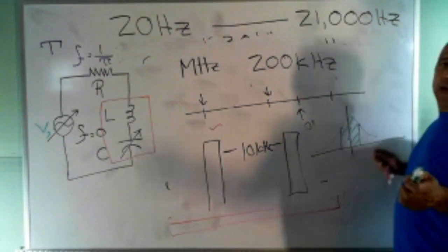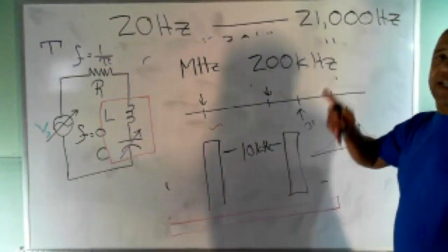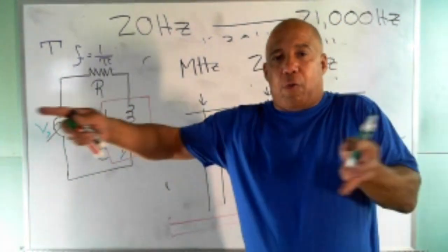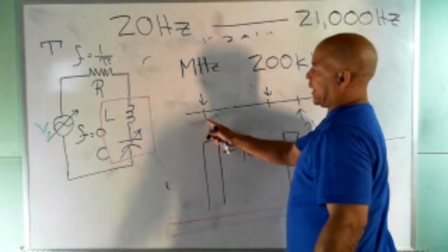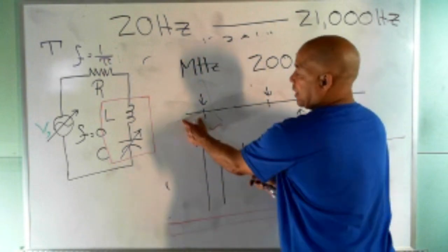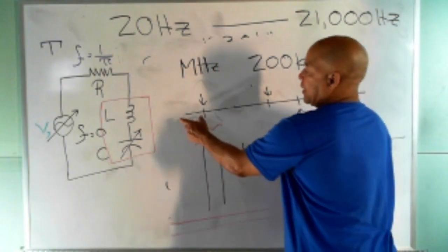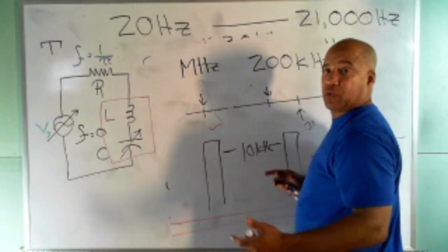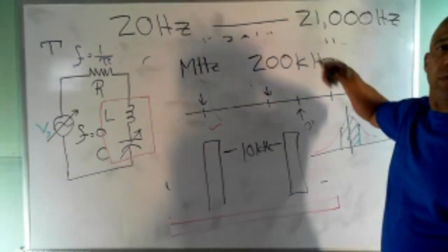When you tune the radio, when you go from one station to another, what you're doing is you're changing the resonant frequency. By changing the capacitance, you're moving that whole band up and down. You can move it up. If this is your resonant frequency, you pick it up. That center frequency F sub R, and then 5 kilohertz this way, 5 kilohertz that way if it's AM. If it's FM, it's 100 kilohertz to the left and 100 kilohertz to the right. The bandwidth is much wider. And so you get all that frequency for human hearing through that bandwidth.